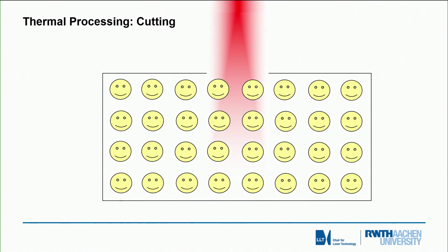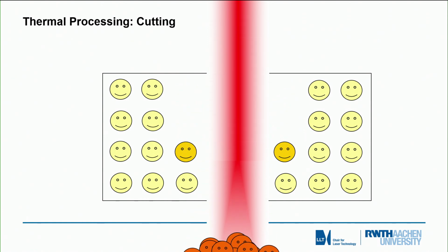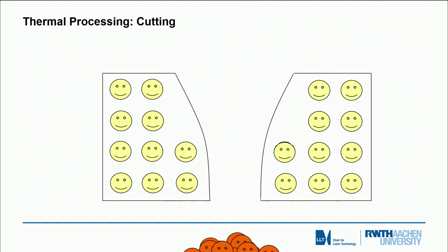we heat the atoms, and then we find the thermal penetration depending on the root of the time, which leads to the fact that we get a temperature increase in the surface and the material itself. And then after exceeding the melting temperature, we can blow out the molten material with a gas jet and get an ablation or a cut or a drill. And the resulting geometry will depend on the recast of the resolidified material.